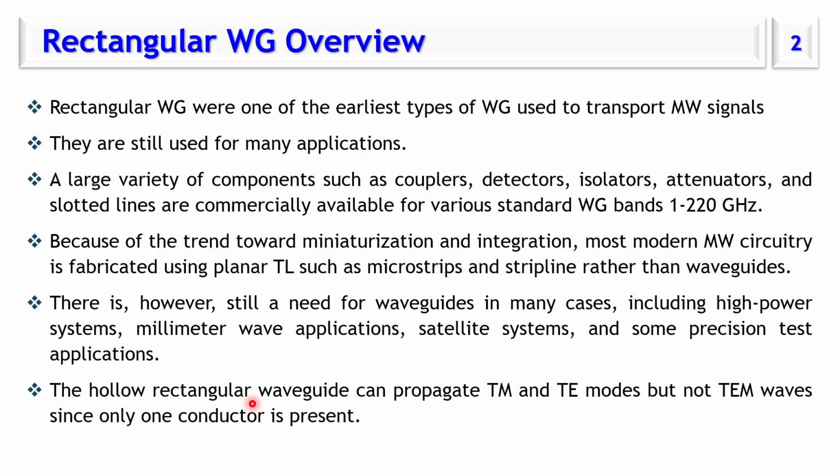So it's more useful. Of course, the planar transmission line or waveguide, like on the PCB, is limited mainly by the amount of power it can carry. So for any application that is high power, we'll go for waveguide structures. For low power applications, of course, the preference will go for the planar or PCB waveguide.